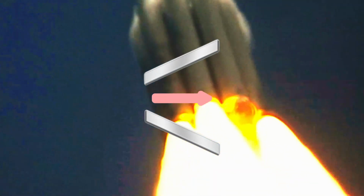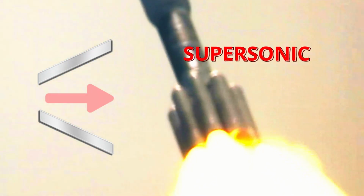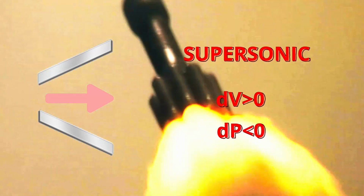In subsonic flow, increasing the area leads to a decrease in velocity and an increase in pressure, while in supersonic flow, increasing the area leads to an increase in velocity and a decrease in pressure.